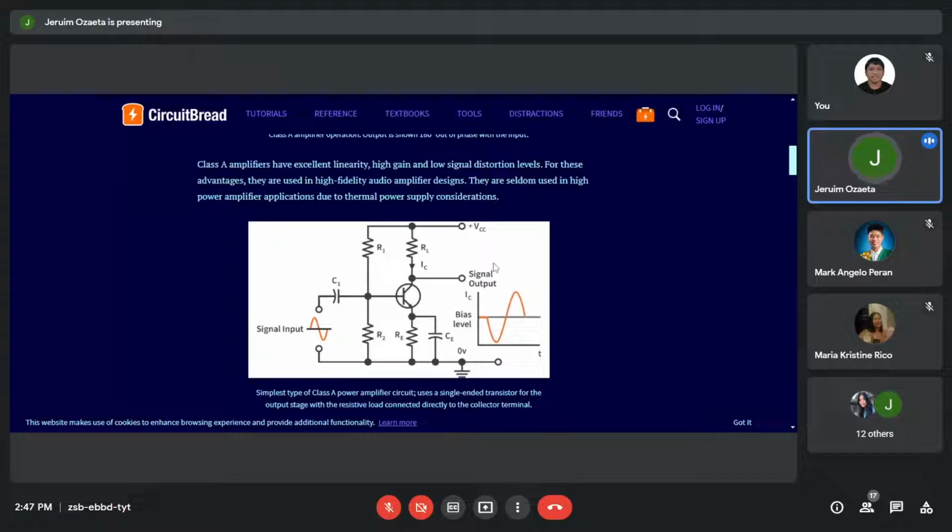Why is that? Because by the time the transistor starts to conduct, the transistor will appear to be a short circuit. And if this short circuit appears across this terminal and across the R sub E, the ground will be seen at the output at that particular moment.